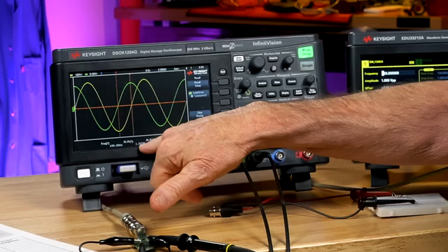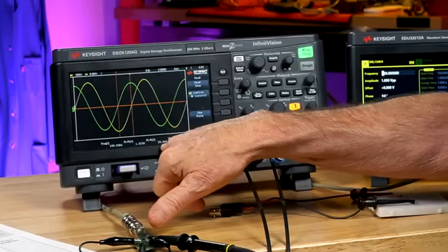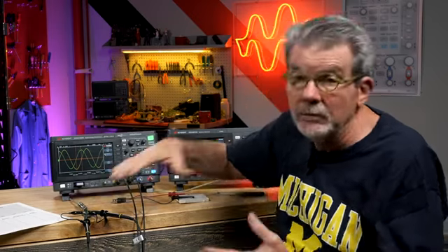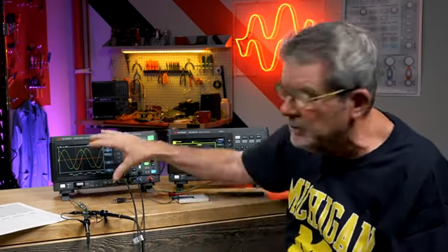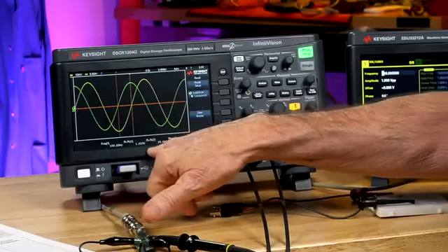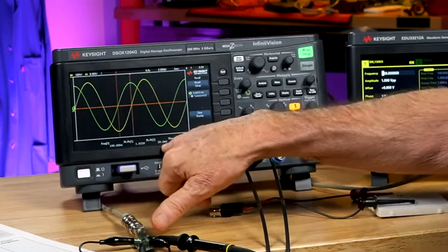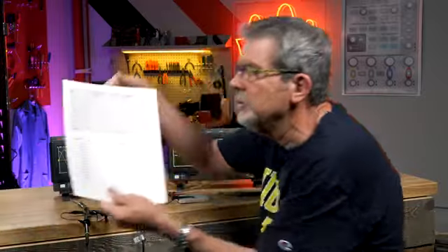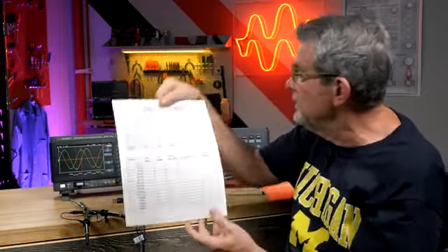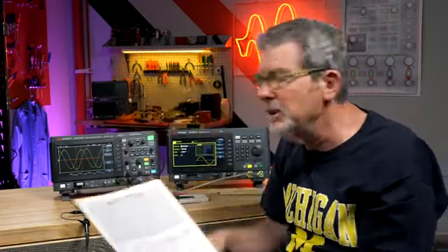It measures about, again, 1 volt peak to peak. That's where I set it on V in. V out measures just 0.028 volts. So V out, the green waveform, is much, much smaller in amplitude. It looks the same. And the phase is about 88 degrees. Now, if you take the ratio, that would be an absolute gain of about 0.028, and take the log of that times 20. That's about minus 30 dB, pretty much what I expected here. And the phase 88, I didn't draw the phase here, but the ideal phase is about 90 degrees.